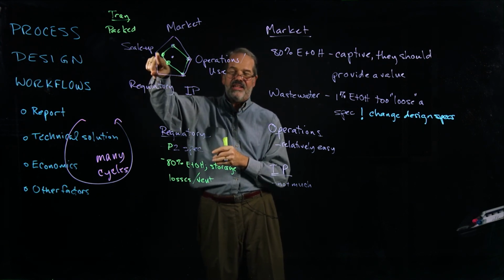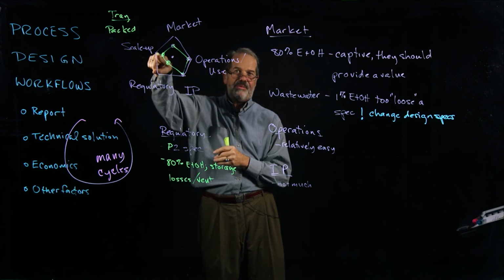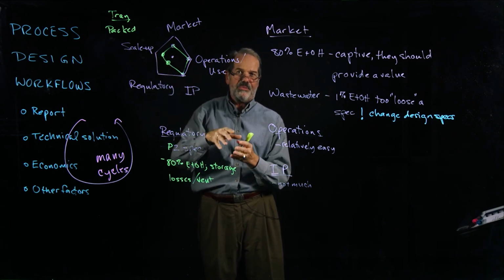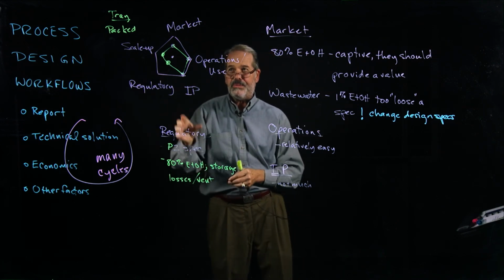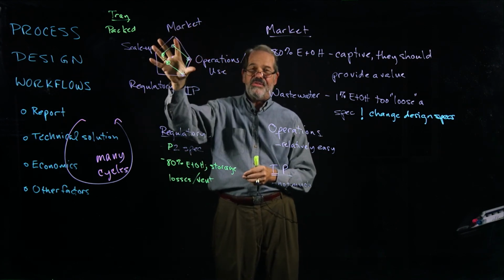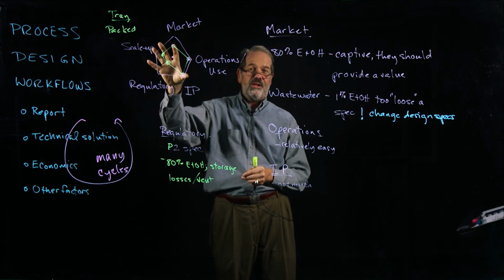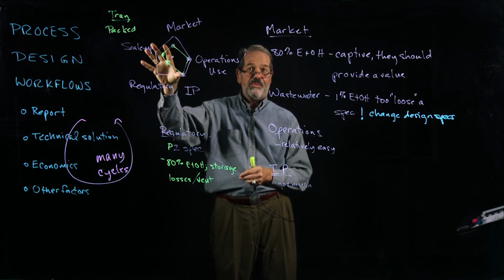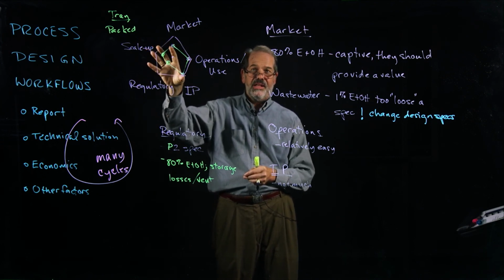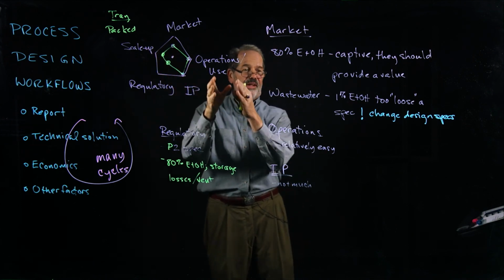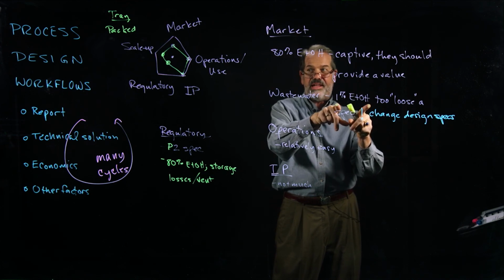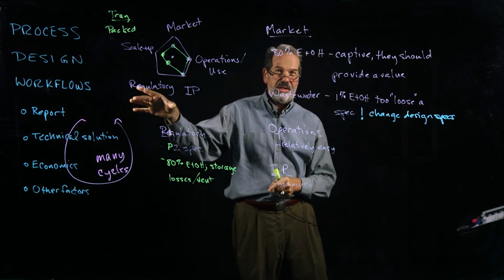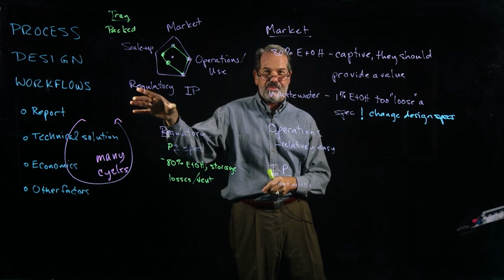And finally, can we scale this up and down in terms of process flow, depending on what the outside demand is? So this little other factors thing is really going to impact where we choose to spend time doing process optimization. It's silly to tune the process to a 1% ethanol bottoms product if that's going to be way too costly and might fail some regulatory operations, for example.